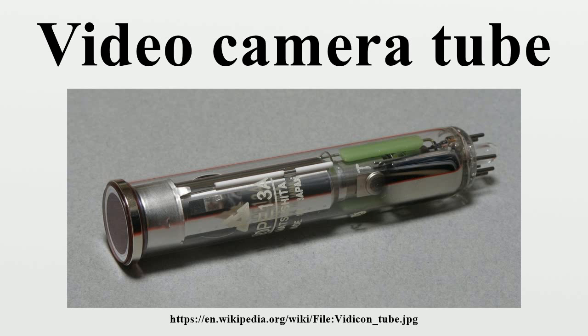The production and commercialization of the Super Emitron and image Iconoscope in Europe were not affected by the patent war between Zworykin and Farnsworth, because Dieckmann and Hell had priority in Germany for the invention of the image dissector, having submitted a patent application for their Lichtelektrische Bildzerlegerröhre für Fernseher in Germany in 1925, 2 years before Farnsworth did the same in the United States. The image Iconoscope became the industrial standard for public broadcasting in Europe from 1936 until 1960, when it was replaced by the Vidicon and Plumbicon tubes.